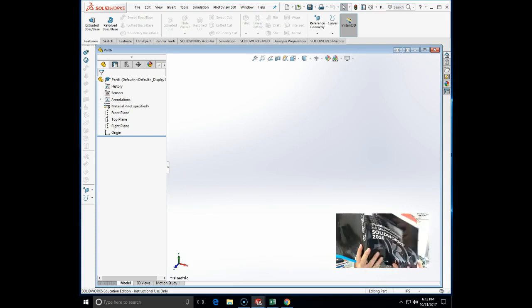So if you go to page 640, we have the major gear terminology, the diameters and other parameters of the gear defined. The SolidWorks toolbox generates the gear as a part for you using the information you provide, like the pitch diameter, the diametral pitch, the module of the gear, which is the pitch diameter divided by the number of teeth, the circular pitch, preferred pitch, the center distance between the two, and so on.